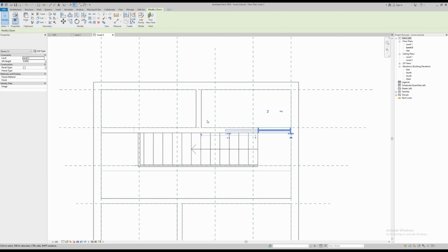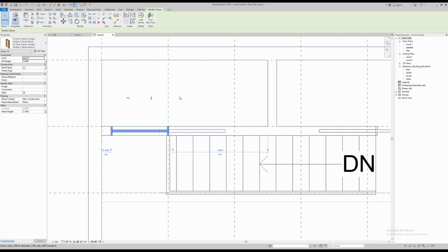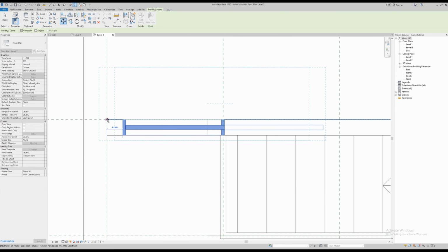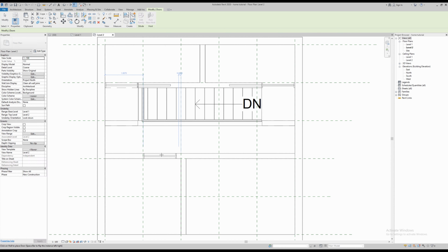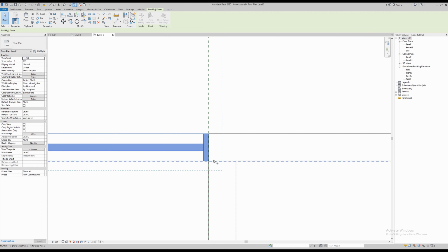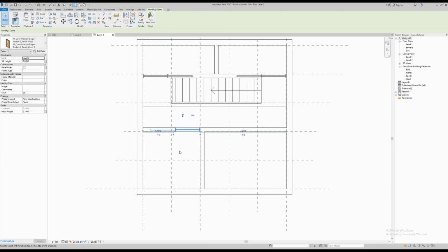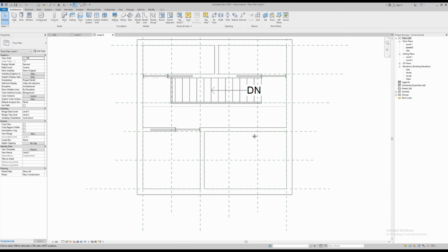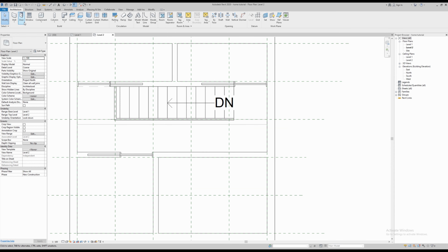Following the same process, now we will mirror this once again, so MM for mirror. I will mirror it to this side since this will be the showering area, and now I will bring this to the wall as well, and I will also copy this one here, so Control C, Control V down to here, switch its side, and now I want to adjust it by the same principle to this wall here, since we want this room to be a bit more private in comparison to this one here, which by having 2 bunks we will leave an opening here for ventilation.